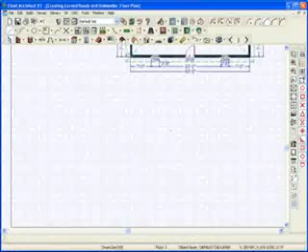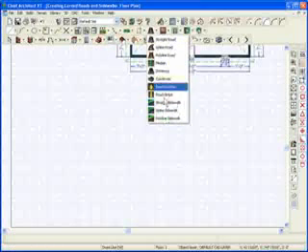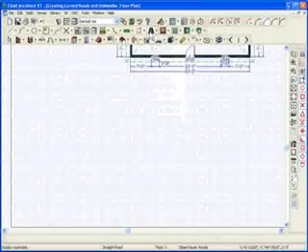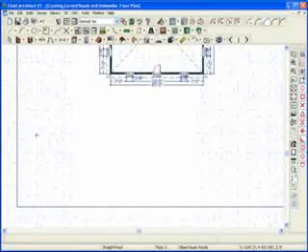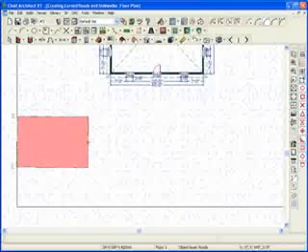Now, how does that pertain to driveways and roads and things like that? Well, I've added a terrain perimeter on the plan. Let's go add the straight road. I could get that icon there and double click on it. I could change the width. I've changed it to 240 inches here. And I could start drawing a road on my plan.